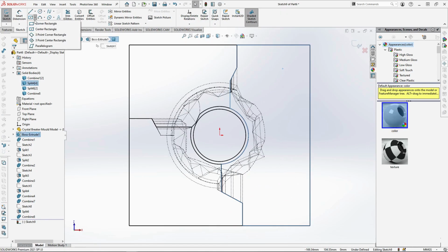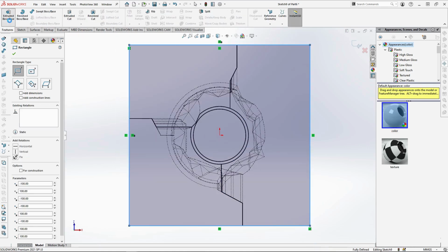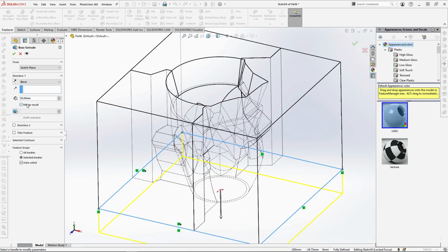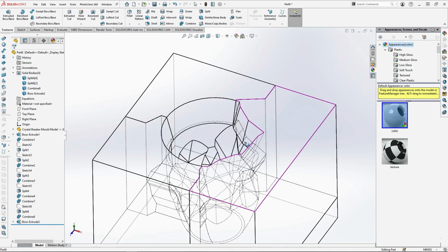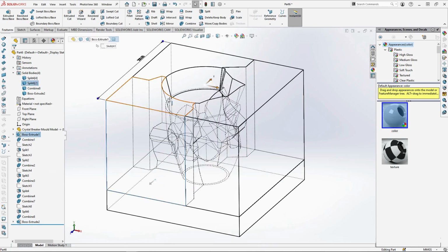Draw a square corner to corner on the moulds like this. Extrude the sketch by 30mm with merge result checked. You need to select the foot ring body for the selected bodies to merge to. We now have 4 mould parts, but to line them up we need notches.